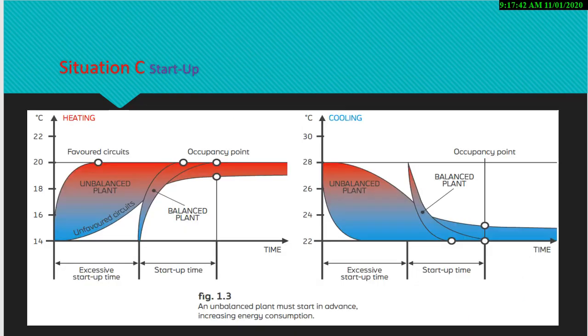And the last situation C, which is start-up. In variable flow rate distribution systems, start-up after each shutdown represents a delicate operation as most control valves are activated while fully open. This situation generates overflows that cause excessive pressure drops in some parts of the pipeline network, while not supplying the terminals of less favored sections of the plant.